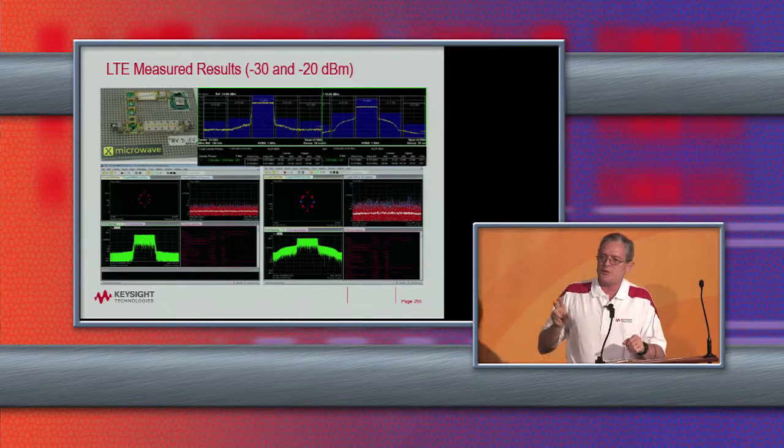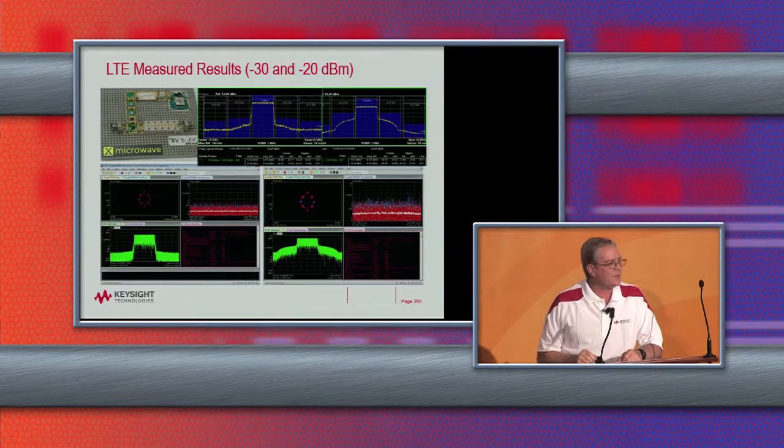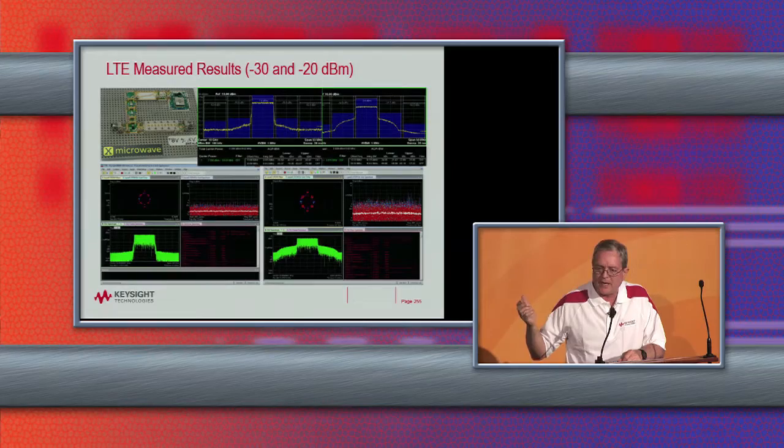Now, what you'll also see here is ACPR measurements using our spectrum analyzer software. You see it at 2 different power levels. Also, our VSA software, and this is how we measured the EVM, and those are the 2 results that you see there at the bottom.